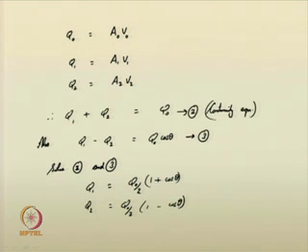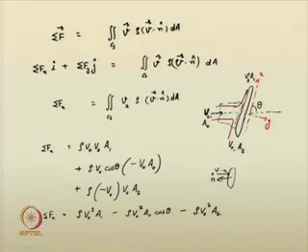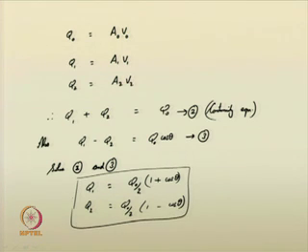So, that is a realistic picture. That is, we only know how much amount of water is coming and hitting the plate, that is the only known quantity to you. How much will be getting splashed in both directions, that you can now measure using this particular theory, using the momentum principle. Now, you have evaluated how to find discharges q 1 and q 2 from the vane, right. So, that way you found q 1 and q 2.